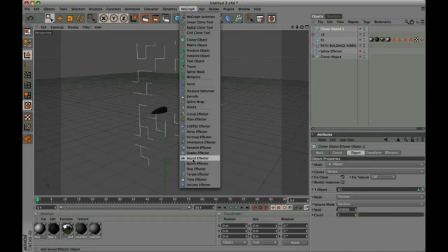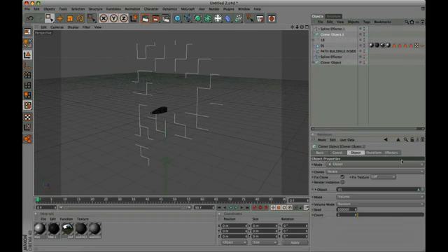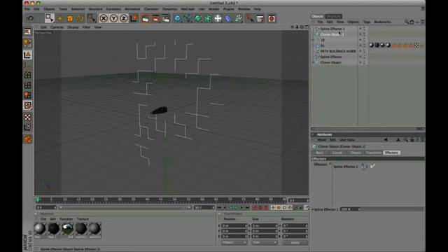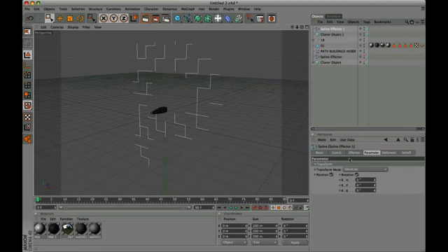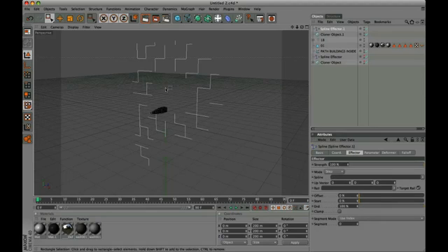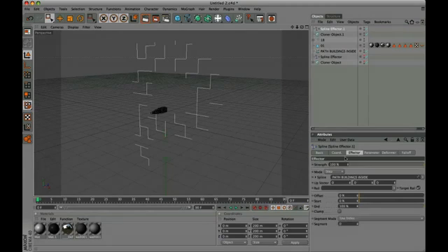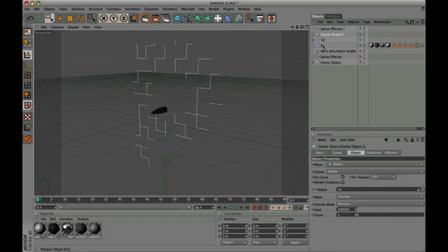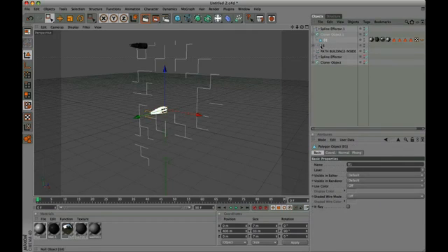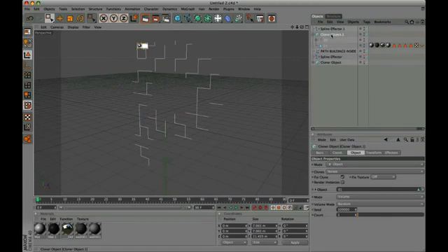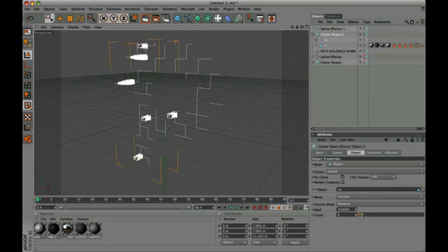With the cloner layer active, also activate the tool MoGraph, Spline Effector. Check if you have applied it to our cloner object. Go to the Effector panel, and on Spline line, drag our path inside buildings. On Parameter, disable Rotation, and on Segment Mode, select Full Spacing. Finally, drag the 01 and 18 models inside cloner objects, and modify the count value to 59.